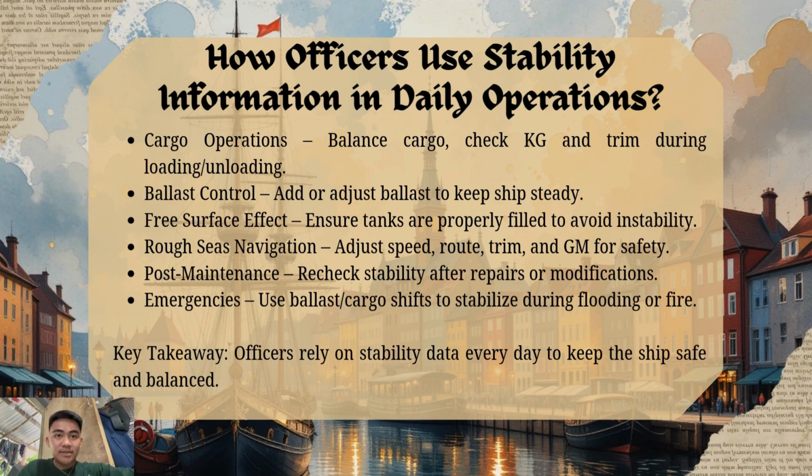Rough seas navigation: adjust speed, route, trim, and GM for safety. Post maintenance: check stability after repairs or modifications. Emergencies: use ballast and cargo shifts to stabilize during flooding or fire.